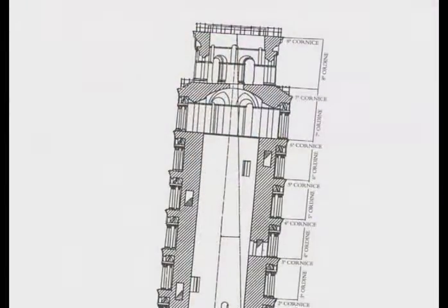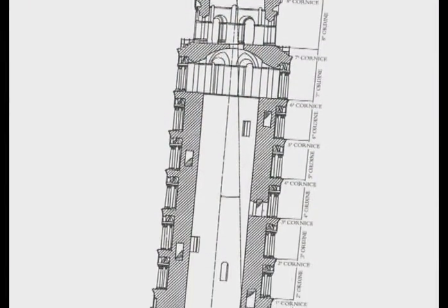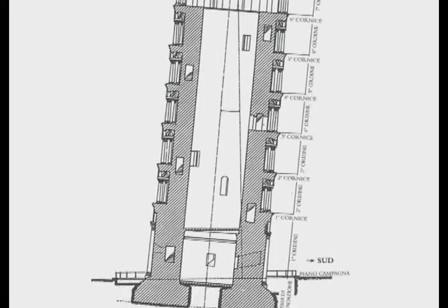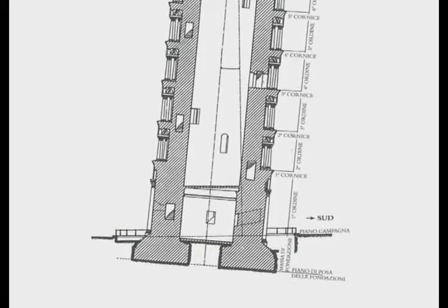Indeed. The thing about the Pisa Tower is that it is founded on extremely soft material. It's founded on very soft silt, and under the silt is extremely soft clay. And the big question is, why is the Pisa Tower leaning? And everybody believes that it's because it must be rock under one side and soft soil under the other. And that's not the reason why it's leaning at all. The reason becomes obvious when you try and build a tower on very soft material.